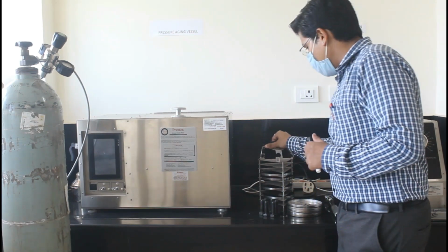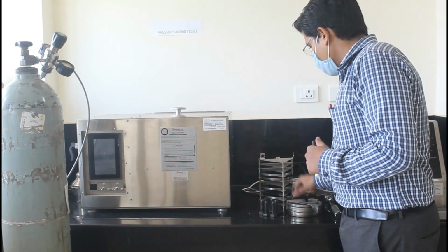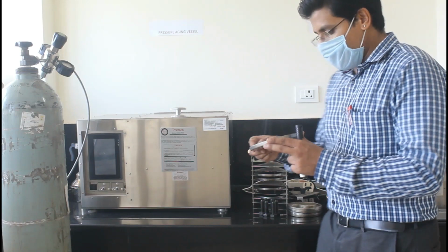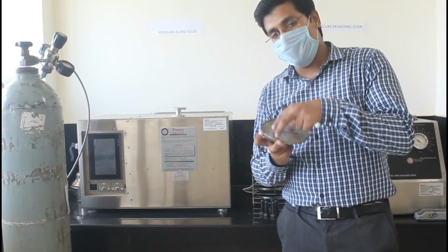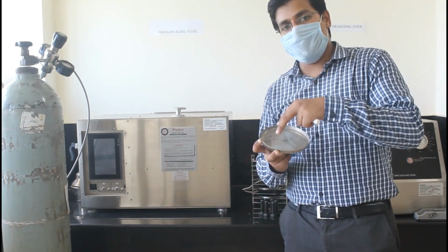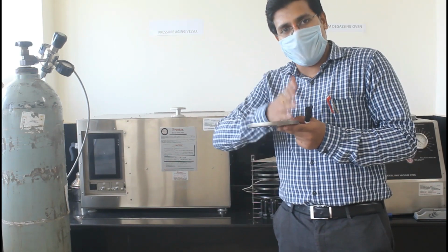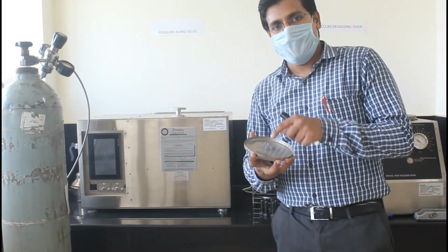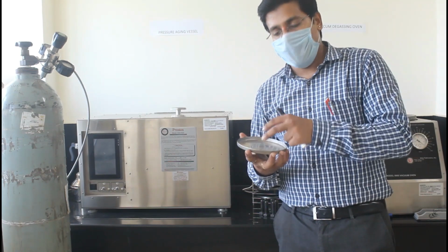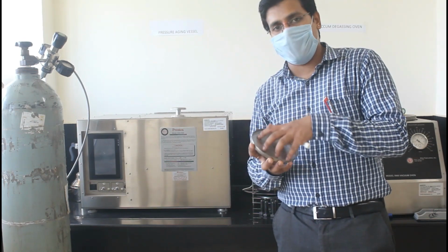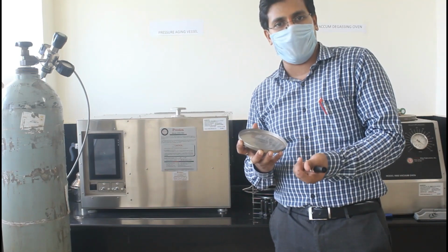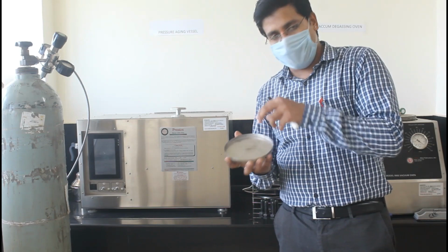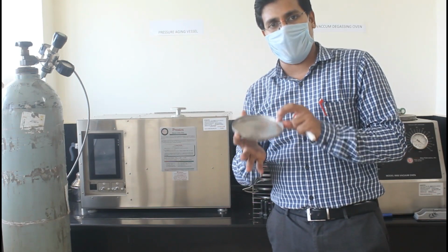And this is the sample plate. This particular pan is the pan on which we pour the bitumen, which is RTFO aged. So it's a step process: first unaged bitumen, then RTFO aged bitumen, and then we age it in the PAV. Whatever you have aged in the RTFO, for example PG 30, you pour approximately 50 grams into this particular plate.